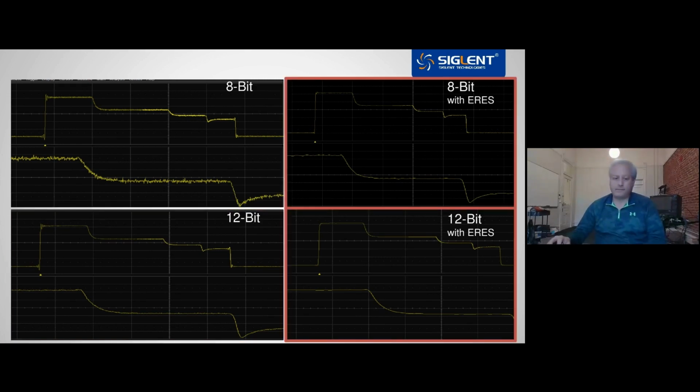Now let's move over to the right. As we look over here, we see we've added some of the filtering capabilities. So clearly, a great way to remove some of the noise. But we can see that it's also attenuated some of those ringing effects and those high-frequency artifacts, as you'd expect. So the real question is for your application, do you want to see that? Or is that unimportant because of the bandwidth of the actual receiver of these signals? So with a combination of tools like this, engineers can optimize noise as well as visual and analytical representation of the signals.